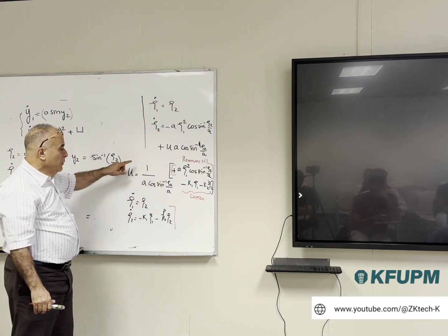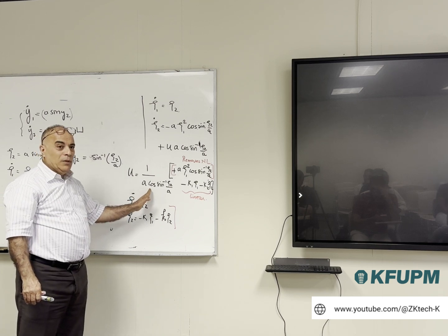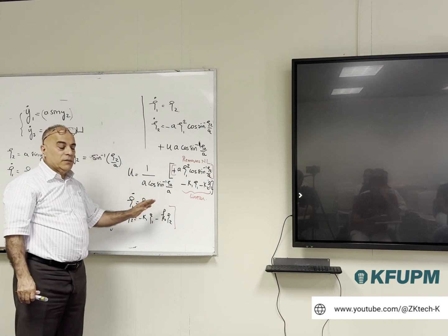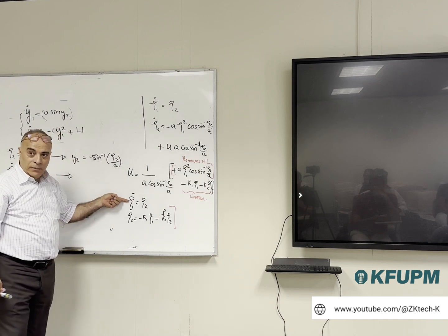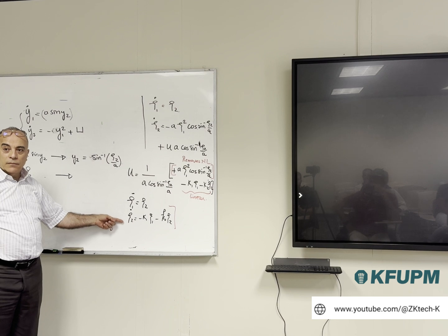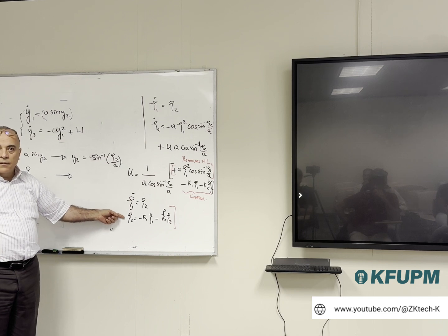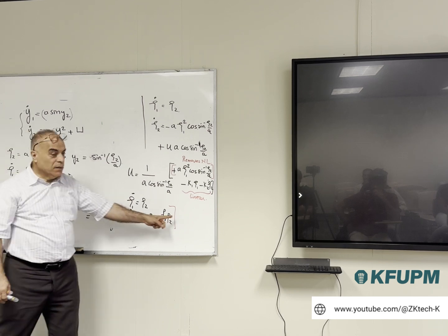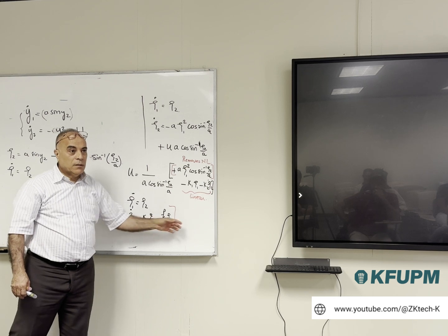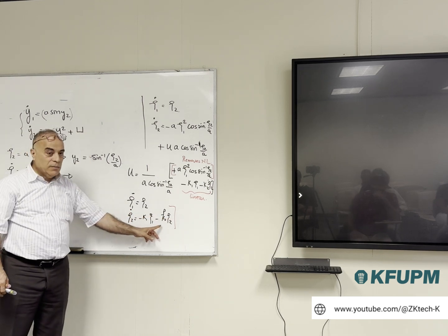The way to go around this is that we define this controller up to a value closer to the equilibrium point. For example, the way I designed it now, at the end, zeta 1 will go to 0 and zeta 2 will go to 0. Right? If I design k1 and k2 such that the system is stable, it will go to 0. So, you agree with this? There is no input. There is no reference. So the system is left to itself, and then it will have to go to 0 so the system is stable.